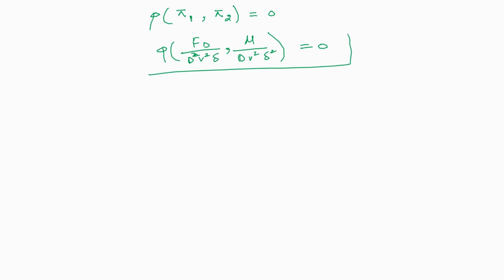So this is the final relationship which is formed between these fundamental parameters, these five variables, Fd, mu, d, v and rho. You can see here in the denominator the variables are same. Meaning there will be three variables which will be repeating in all the pi groups, and there will be one variable which will appear once in each pi group. In the first pi 1 we have Fd as a non-repeating variable, and in the second pi group we have mu or dynamic viscosity as the non-repeating variable. So I hope that this discussion will help you understand the basics of Buckingham's Pi theorem.